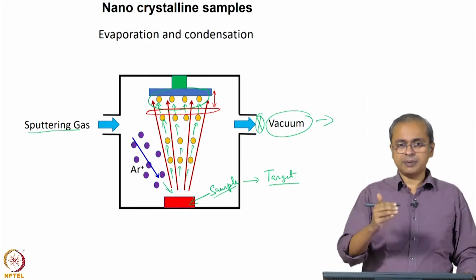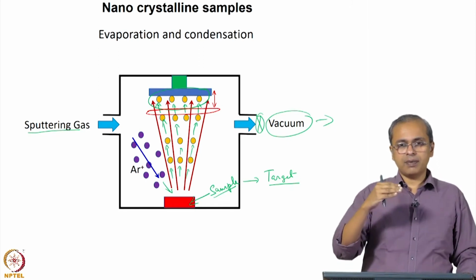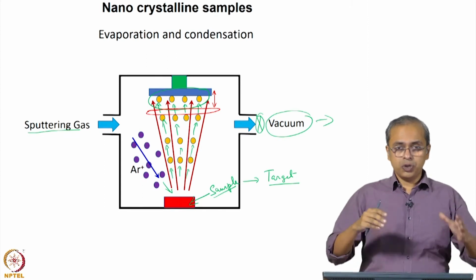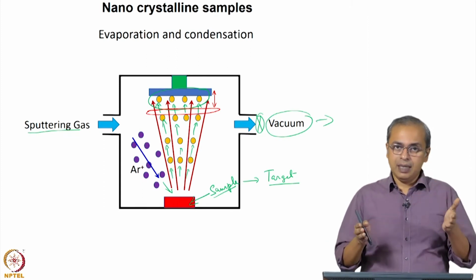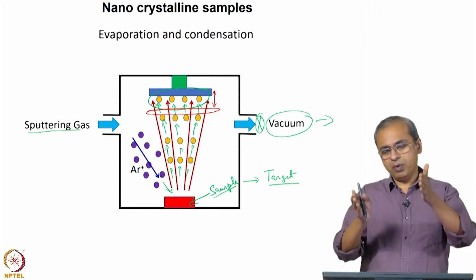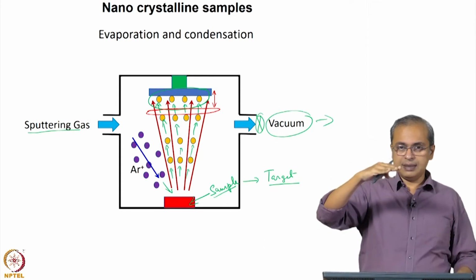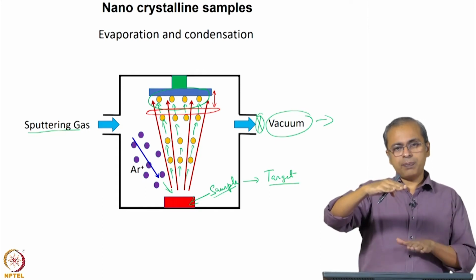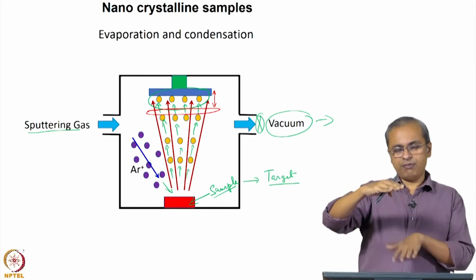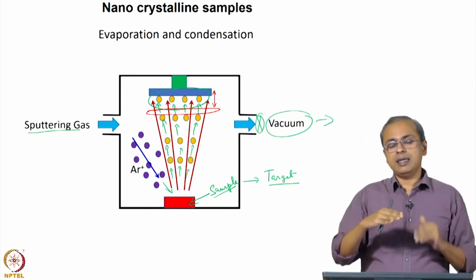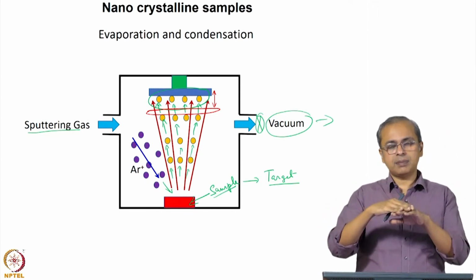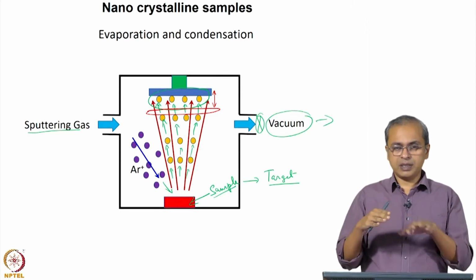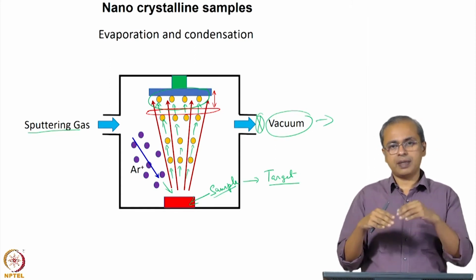So it is between the substrate and the target, and it blocks whatever is coming from the target from reaching the substrate. So usually what will happen is, in these experiments we start the process, we allow some amount of sputtering to go on with this mask blocking the path, and at that point any impurity that is getting released from that sample will not reach the substrate. It will get blocked by this mask, it will maybe form a layer on the mask, and that is useless for us. So it just continues to form for some point in time.